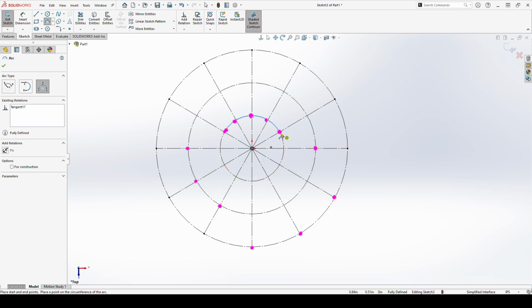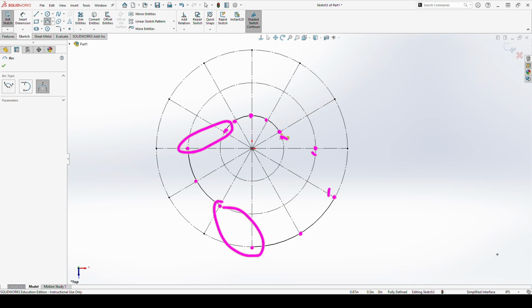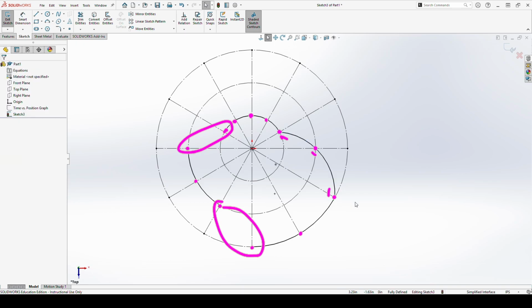And at this point, you can actually see it because we've got a solid line. I've got a 3-point curve for here to here. I've got a 3-point curve from here to here. And I've got a 3-point curve from here to here. However, I am still missing one 3-point curve, well, 2 3-point curves, because between here and here, and between here and here, I don't know what's going on. Which means that I'm not quite done, and this guy just didn't end up coincident.